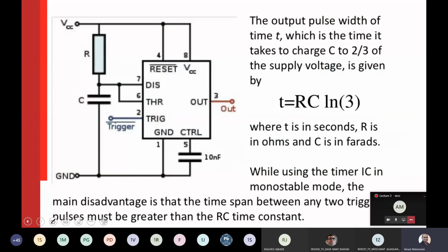So we are going to make this circuit practically also in the lab, but just see here, we don't want to reset the IC. So always remember, whenever you are connecting IC 555, pin number 4 and 8 should always go to VCC unless reset is required. Now, since it is written reset bar, there is a NOT gate, and that's why when you pull this pin to VCC, you are not resetting the IC. Okay, so remember, your pin 4 and 8 should be shorted together and go to VCC.